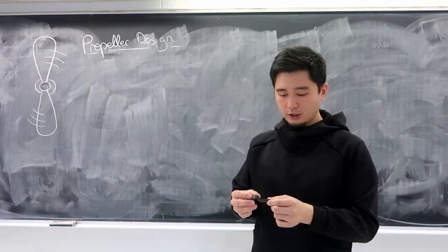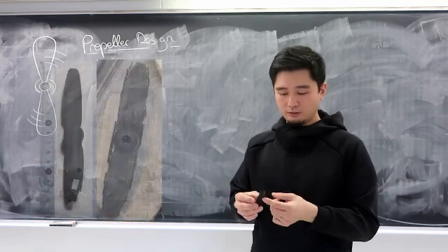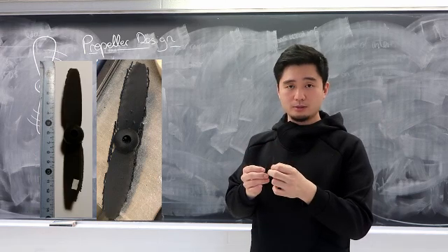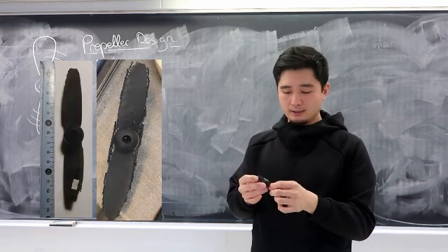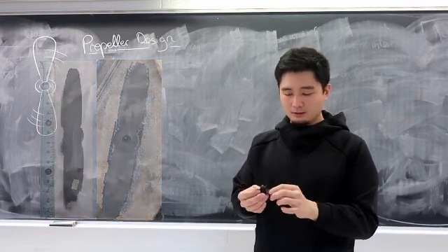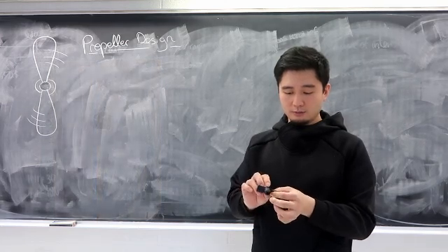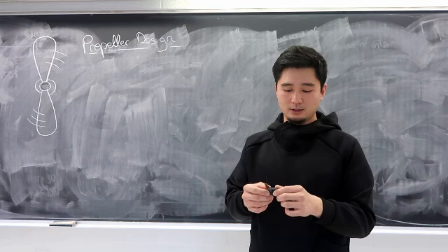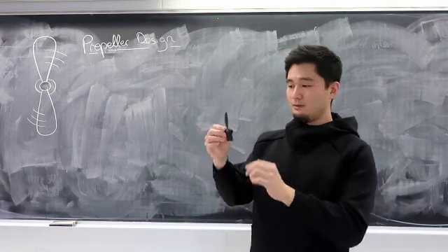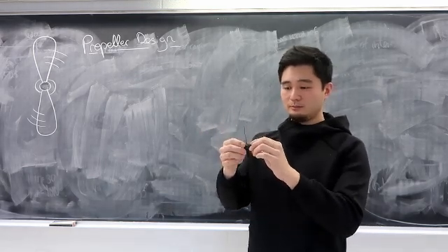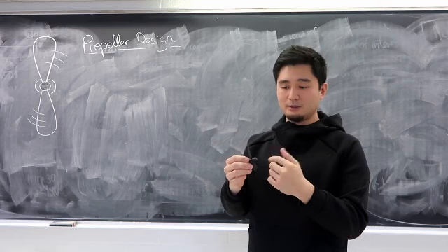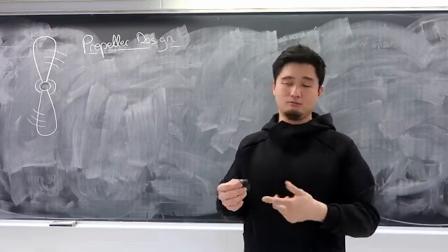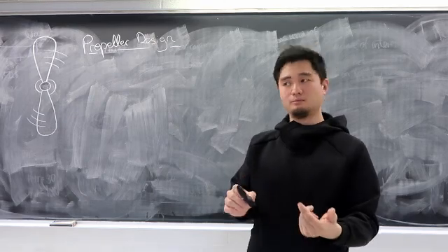During the conduction of the test, the finishing of the surface was a little rougher than we thought. So when we broke it up, you still have to see a little bumps near the trailing and the leading edge. Another thing was that the direction of the rotation was different than what we thought. It was actually counterclockwise, so the twist angle of the propeller is actually in the opposite direction, so all of our test data came back negative, but the values are still valid. It's just instead of propelling, we're propelling the other way.